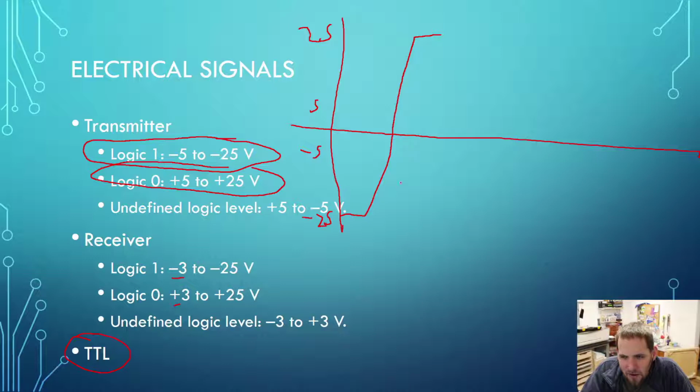There's always going to be a little bit of a slope to that line. The longer your wire, the longer this transition is going to be, and that's because of capacitance. And again, we'll come back to that one either in a little bit or next class. So we like those high voltages, but we don't always have access to those.